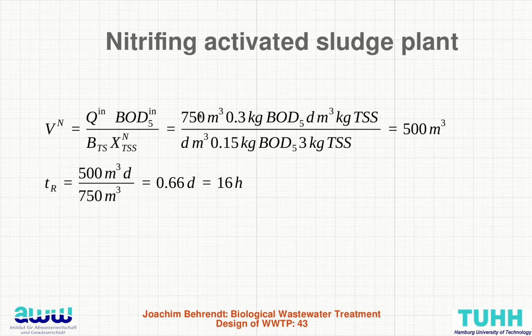And then you have this 750 cubic meters, this 300 kilograms per day per cubic meter BOD, and divided by 0.05 kilograms BOD per kilogram TS a day, and 3 kilograms TSS per cubic meter. This ends up in 500 cubic meters. And then you have the inflow rate and the volume, and this ends up in 16 hours hydraulic retention time.